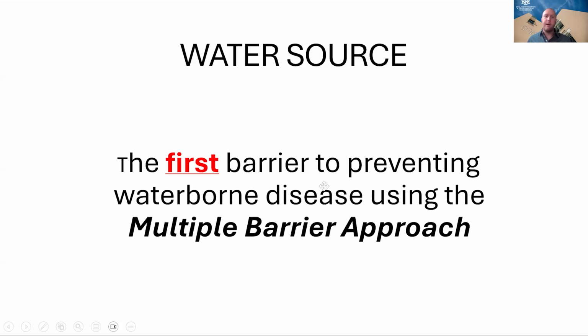Okay, so water sources, this really is the first step in the multiple barrier approach. Where your water is coming from is really the first step where contamination or disease could occur. So having a safe water source that's well protected from contaminants is that first barrier in the multiple barrier approach. And I bet some of you have heard that term before.